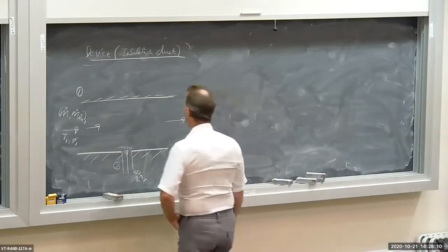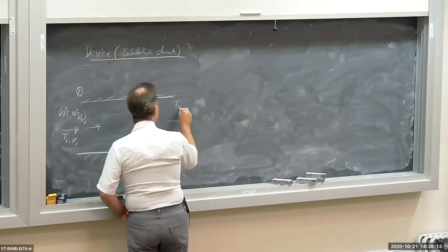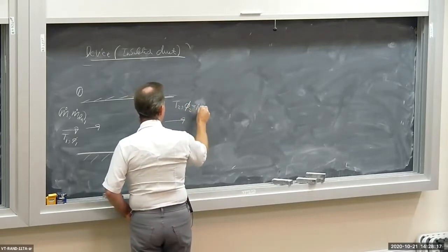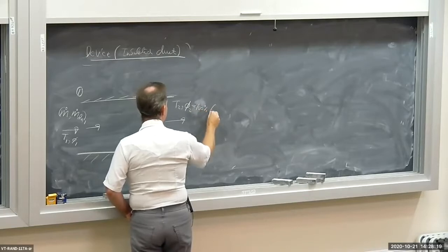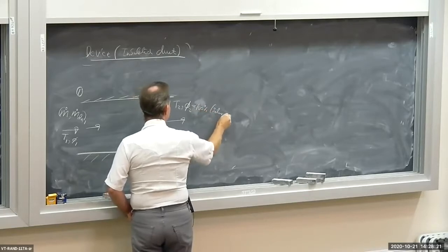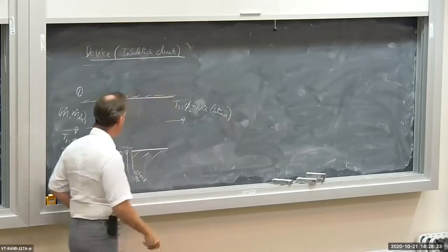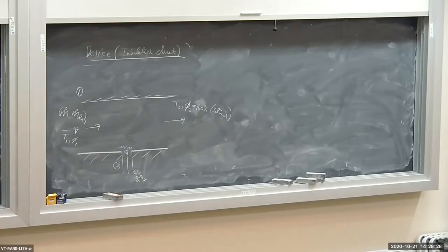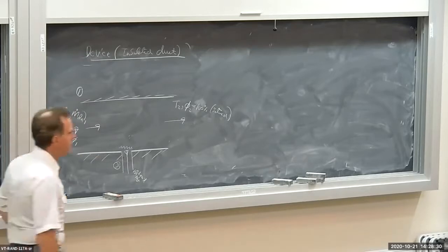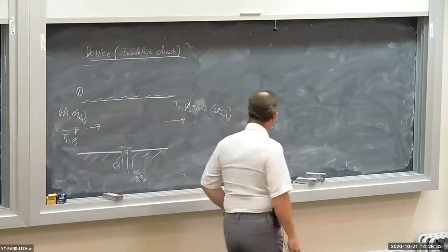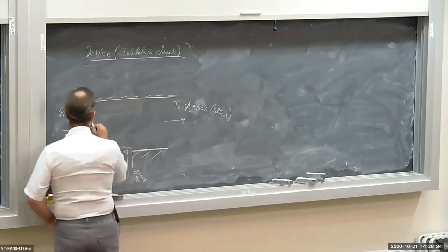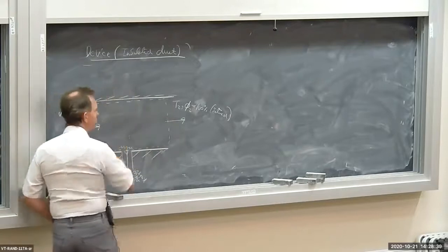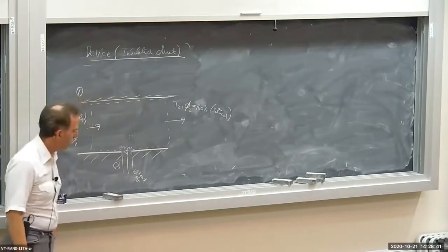And at the outlet, I have a temperature T2, and I have a relative humidity equal to 100%. So it is saturated at the outlet, okay? We're adding H2O, and the H2O is evaporating, humidifying the air until it's saturated at the outlet, okay? So my control volume here, here's my control volume. Clearly, this is an open system, okay?